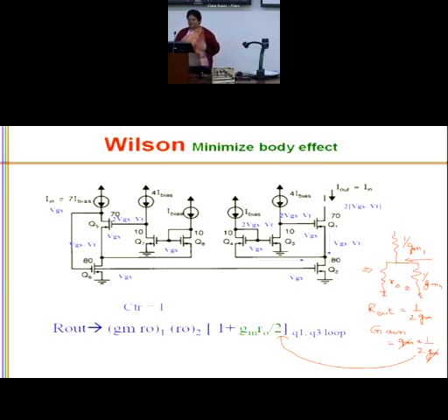And this is where you have a connection. So you can see it is a low voltage cascode. This node comes to VGS minus VT, 1 V overdrive, and this node also comes to 1 V overdrive. So there is no lambda mismatch between IREF and I bias. There is no lambda mismatch.